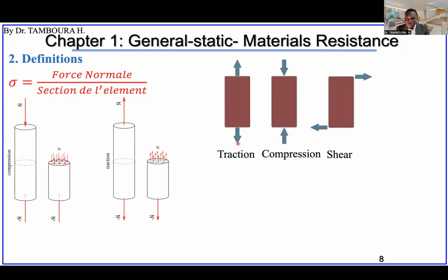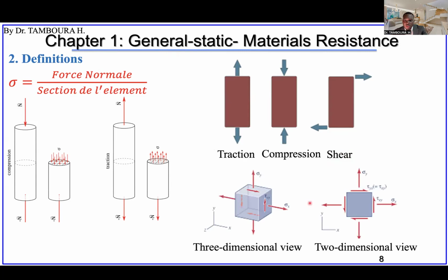This force is normal to these sections, right? Here also, the force is normal to the section. However, we can see here, in the same section, these two forces are not normal to the section. They are not perpendicular to the section; they are parallel to the section. In that case, we will have shearing stress instead of normal stress. So be aware that it is not always normal stress.